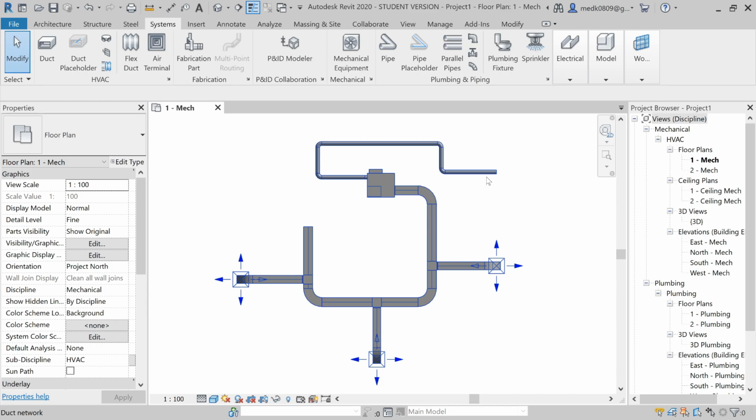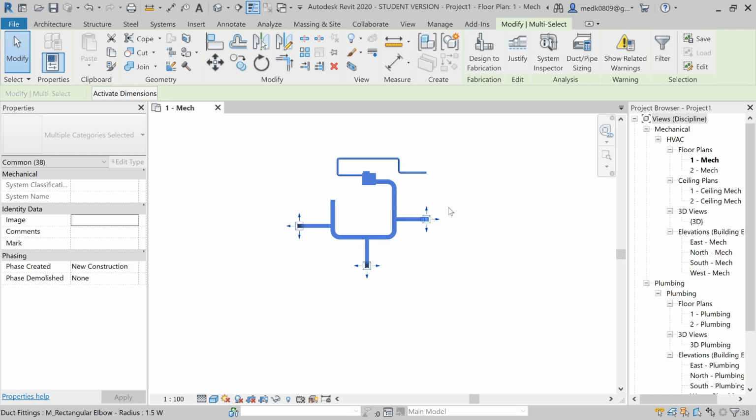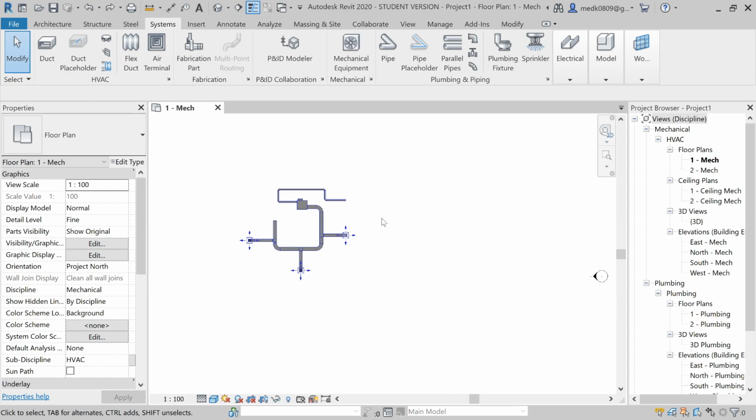Now you have to just click. When you will click from your mouse, you can select all the circuit. So this is how you can select the circuit with the help of tab key. Now the next command we have is move. For that let's select this circuit.